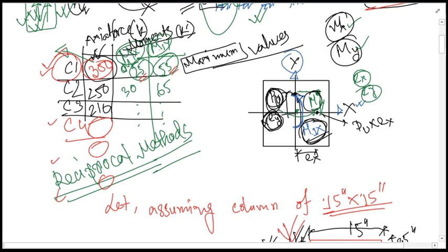Similarly you will fix the edge columns and show that all the edge columns satisfy the needs according to your provided reinforcement, and the middle columns accordingly. So you'll have to choose 3 column types and finally show that all these are satisfying this. That is your task while designing columns.